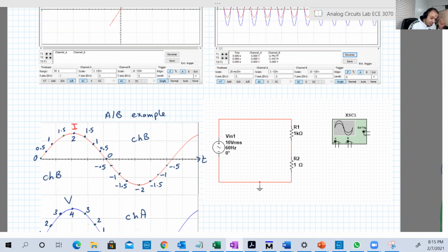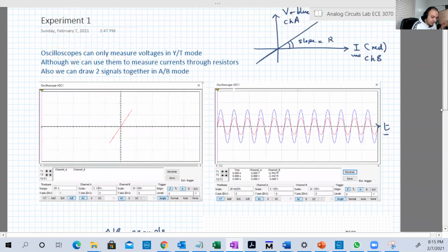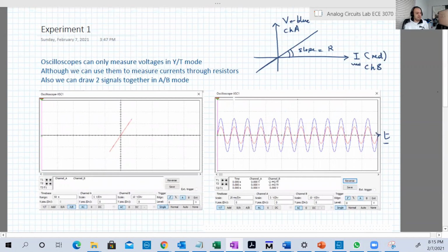So, in the first lab, we studied Multisim, but the purpose was to verify Ohm's law. And we used two methods for that. The first method is a traditional, intuitive method. You just change the voltage on a resistor and measure the current at the same time, make a table, and draw the relation, Ohm's law. Okay, measure the slope, which should be the resistor.